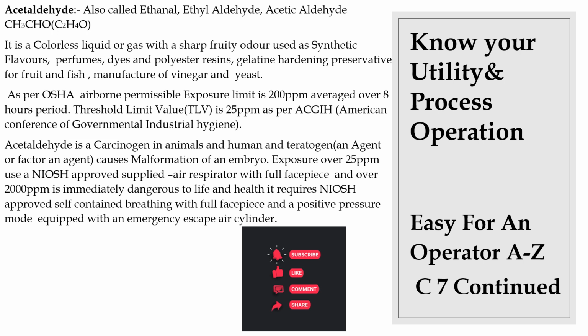As per OSHA, the airborne permissible exposure limit is 200 ppm, averaged over an 8 hour period. The TLV, the threshold limit value, is 20 ppm as per ACGIH, the American Conference of Governmental Industrial Hygienists, an important agency. Acetaldehyde is a carcinogen in animals and humans, and a teratogen. It is an agent or factor that causes malformation of an embryo.